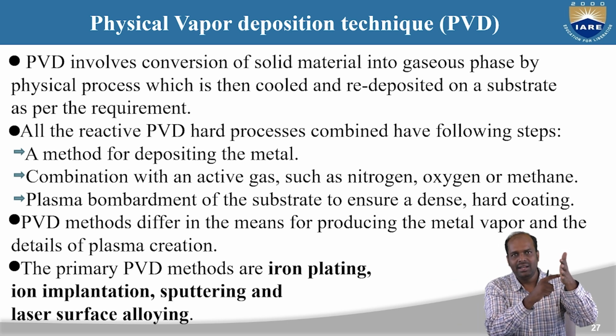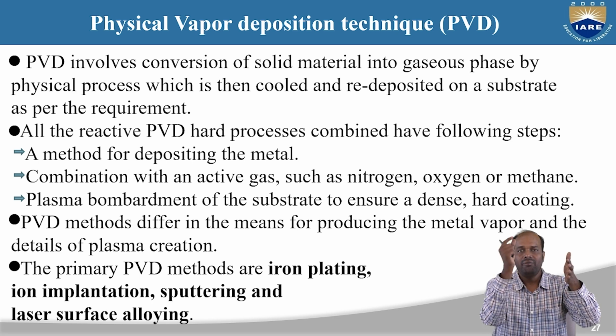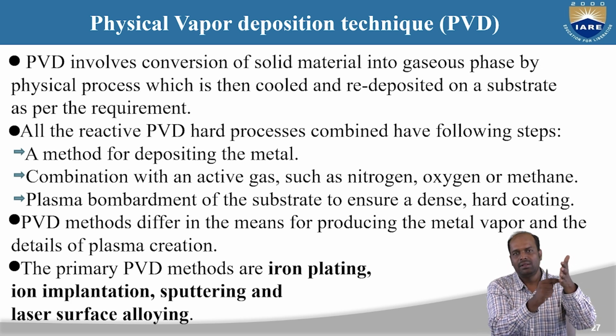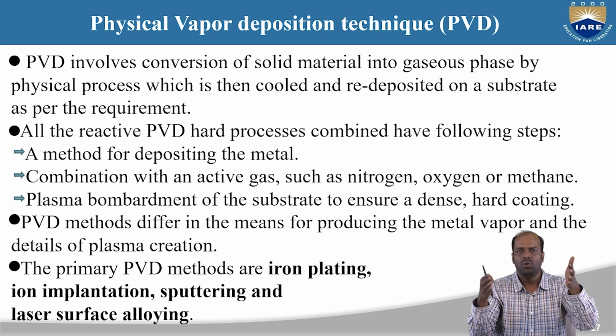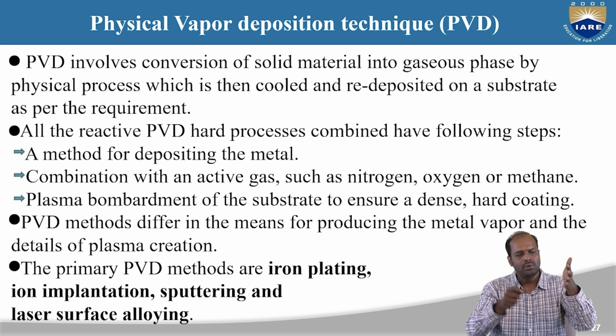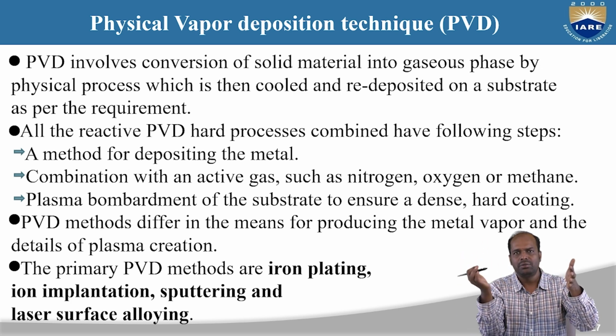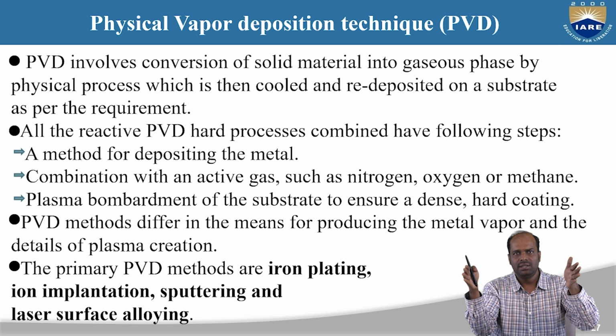This target that we are keeping is a compound of your precise compound. Suppose you are taking lithium cobalt oxide, you keep the target as lithium cobalt oxide. You want to coat this lithium cobalt oxide target material onto a substrate, either glass, silicon, ITO, or any aluminum foil or copper foil. So this material is going to deposit over the sheet.